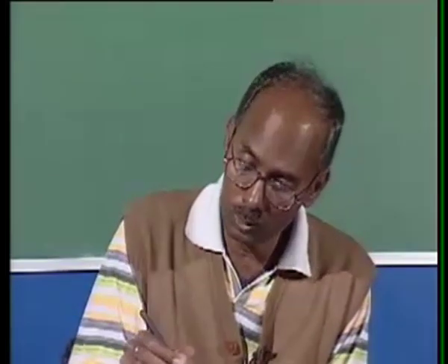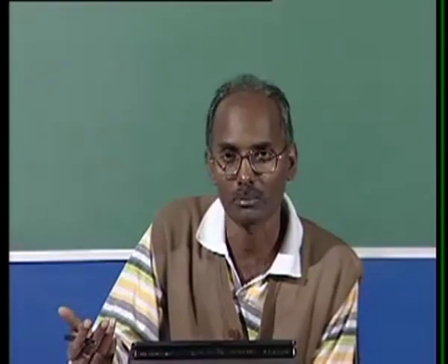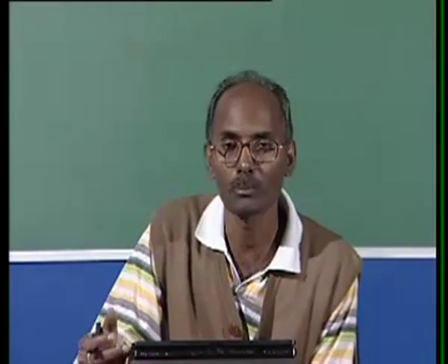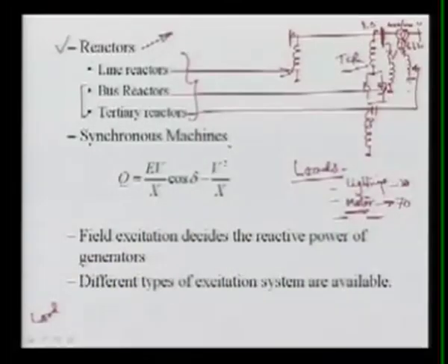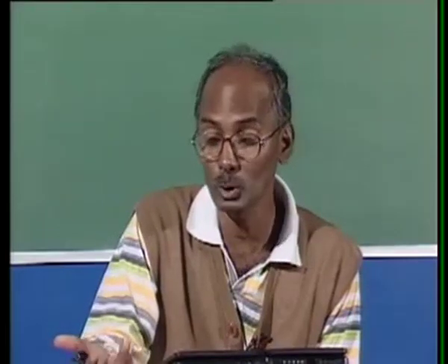So the motor loads are the most, and for motors, there are two types. AC motors are available, that is synchronous or induction. In most conditions, we use the induction motor because it is very, very versatile, rugged and reliable. So we use the induction motor, and you know the induction motor is nothing but just like a generalized transformer. A transformer consumes reactive power.